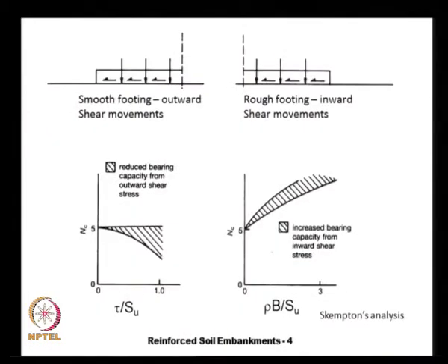And now let us go to the topic of today's lecture, that is the construction of embankments on Geocell matrices. The concept for the design of Geocell matrices goes way back to Skempton's analysis, who showed that for smooth footings the shear deformations are outward deformations.